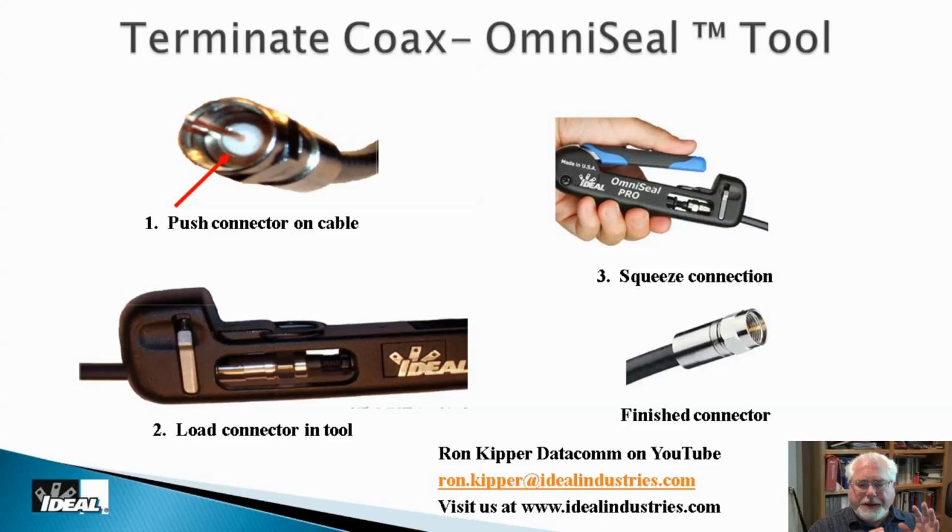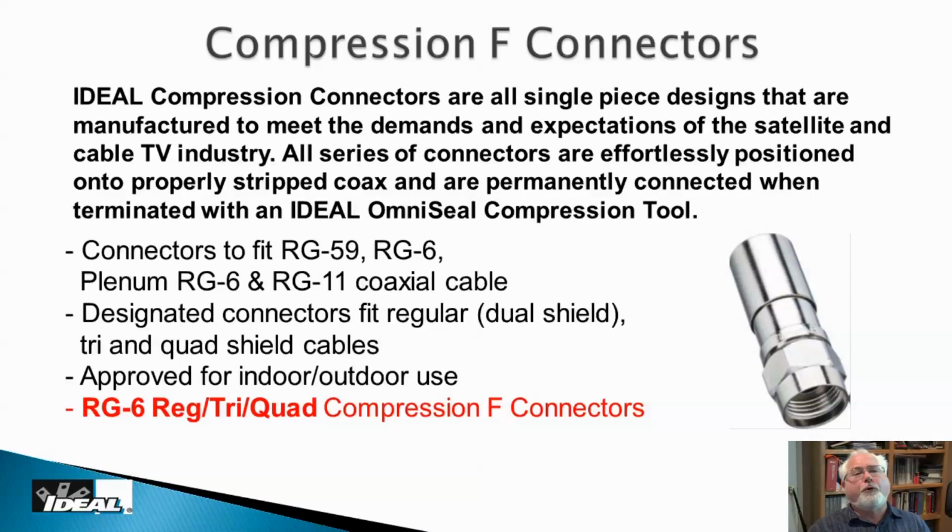Now the tool is designed to compress the connector all the way down, and the tools are adjustable. I get guys in classes that get about halfway down, the tool's been out of adjustment for some reason. And they're in the back of the room, squeezing as hard as they can on this darn tool, and they end up crushing connectors in the tool. So be aware that you can do that.